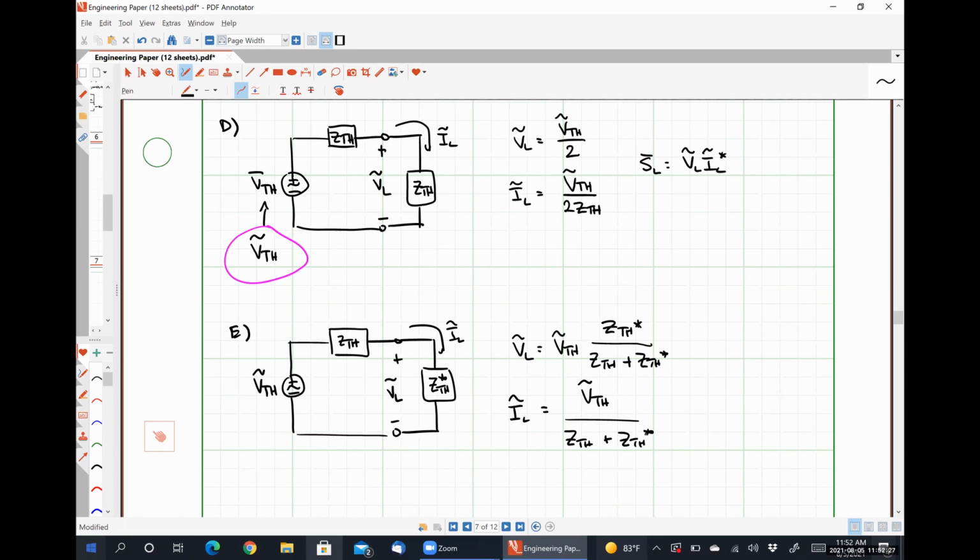If not, you were just given the phasor voltages, and so you need to convert simply by dividing by the square root of 2. I want to make that very clear, because if you don't recognize that, you could be working the problem perfectly correctly, except for that small subtle difference, and find yourself getting the wrong answer and getting frustrated.